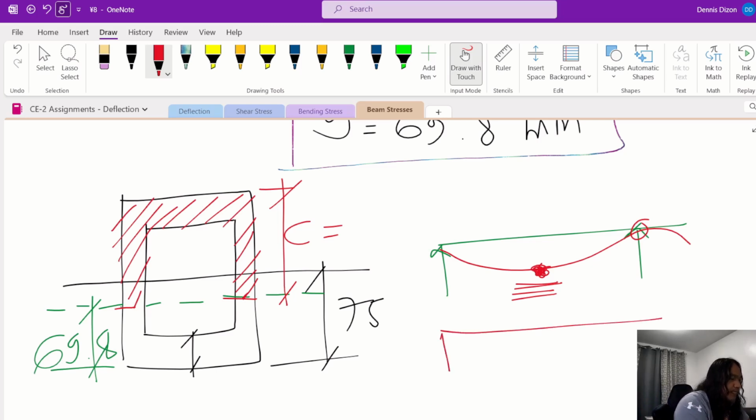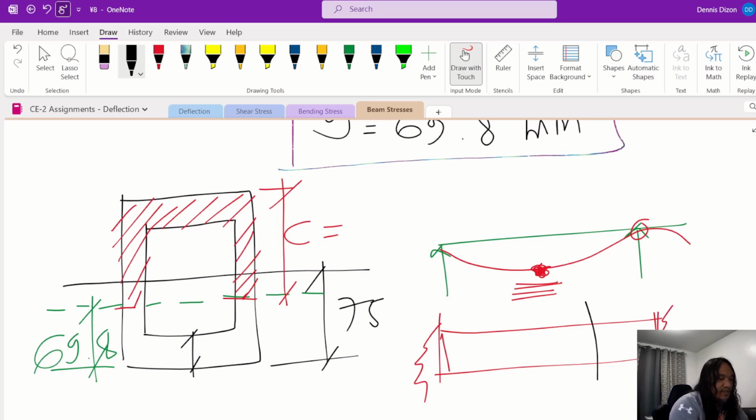if you have this beam, and assuming this is a rigid connection here, the rebars near the support, this is the point of inflection. This is L over 4. This is where the change in curvature is. This is L over 4. This is L over 2. So the rebars right here are at the top because this is in tension.